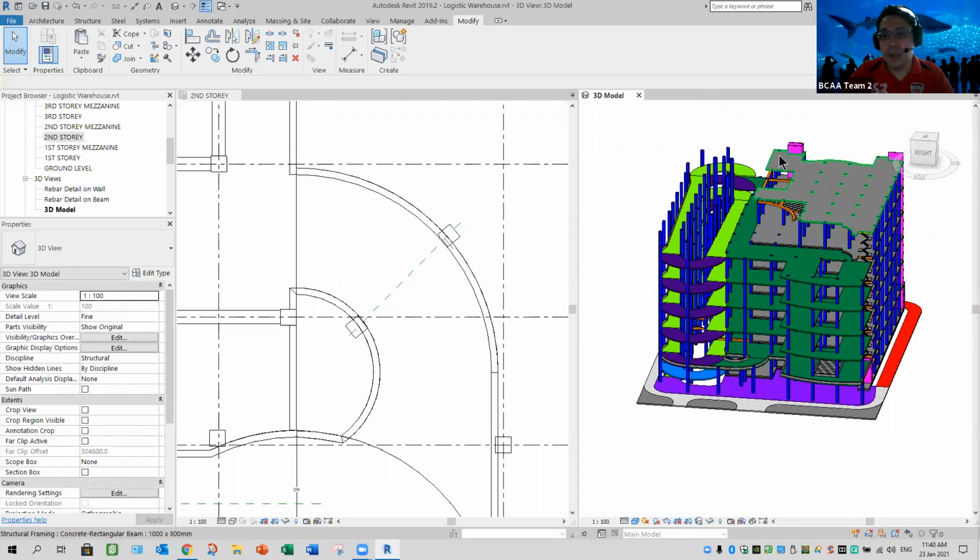Roof has nothing much, only the ceiling, but here I believe you still have to add the parapet. But this parapet here need not be 500. It should be thinner. All right, set it to 200 will do. Because here should be a garden park, something like that. So you need to have a parapet wall surrounding it. Okay, follow the profile. Should be around 200. The height, try to adjust it to 1.2 or at least minimum 1.1.